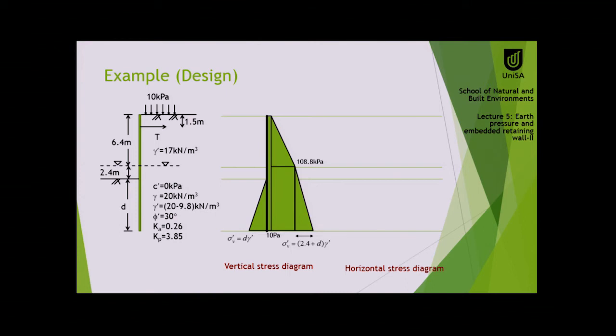So what I tried to do over here, I drew a mild slope. It was increasing at 17 rate. Now it's hopefully increasing at 10.2, or not 10.2, 17 minus 9.8 rate. So it would be 7.2 rate. Got the idea? We can use gamma prime to calculate those directly to effective stress.